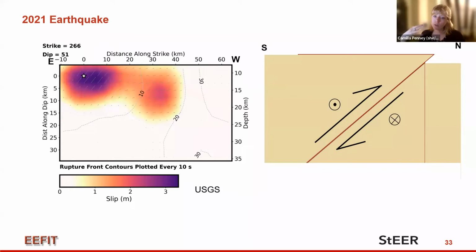So I'd like to leave you by saying that it seems there's more work required in terms of how we understand the faulting that's actually going on in Haiti. In particular, to emphasize the cartoon on the right here, demonstrating that as well as the strike-slip motion shown by the circles, which has long been recognized in this region, we also have to be thinking about dip-slip motion, which might lead to broader regions moving or different expectations of the ground motions that might happen in these earthquakes. And now Mobin is going to talk to you about what those ground motions actually were in this earthquake.